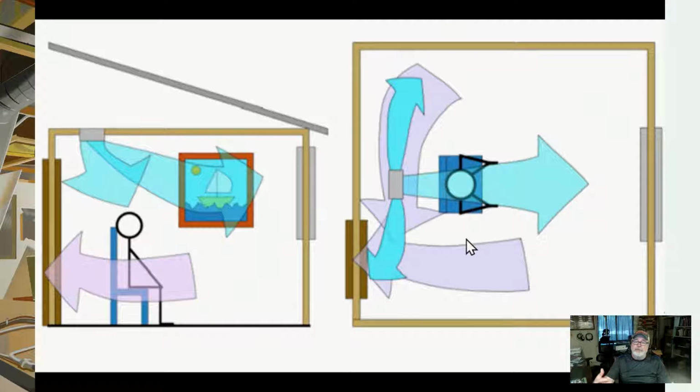The second one is interior to the room, blowing across the room towards the load. That should either be a three-way register or a one-way register. They actually make one-way registers too. It's blowing towards the wall, but then you have to worry about throw distance and making sure the air is not stopping halfway across the room. And then you get stagnant areas and stuff like that. So that's school of thought number two.